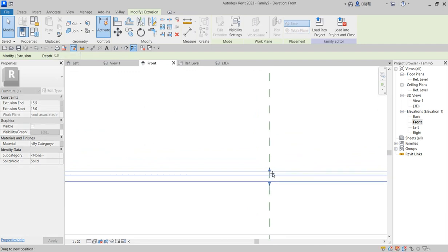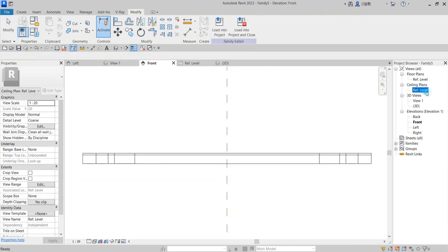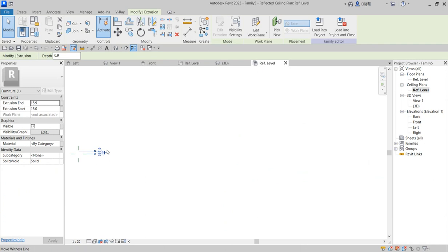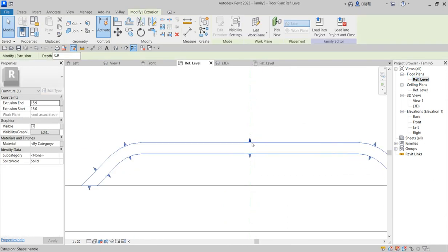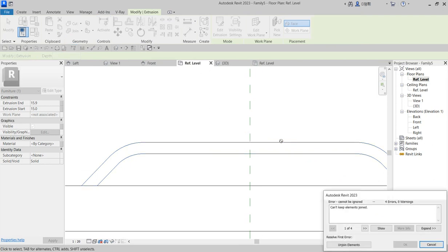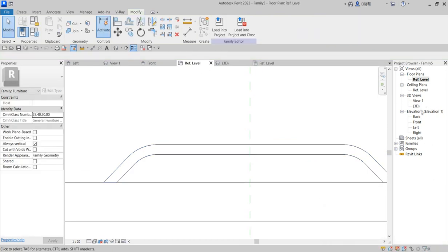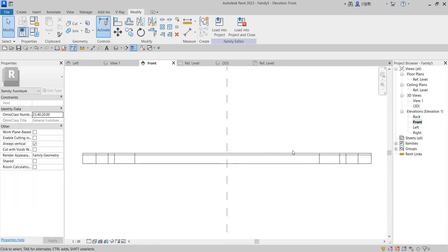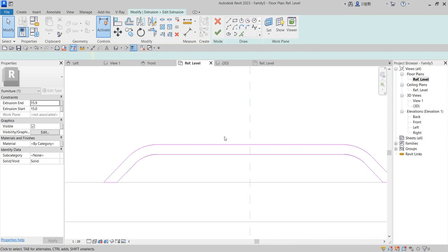So increase it a bit. Good. When you go to the floor, to the plan, to fill it from plan, now you can extend this or click and just say front select. So go to the top and say extrusion.